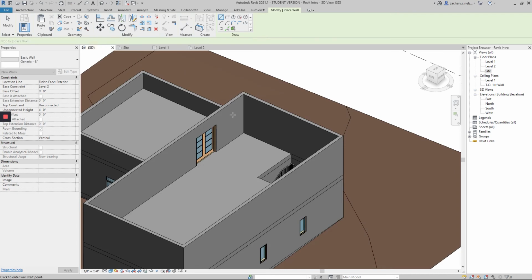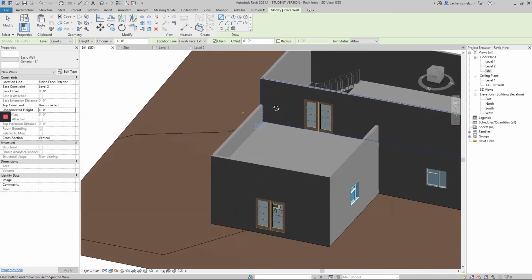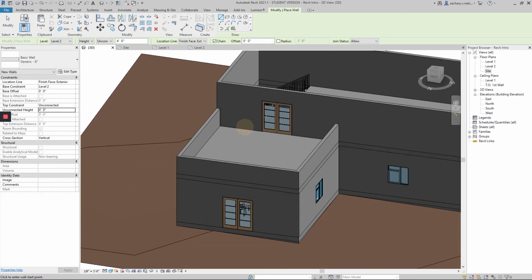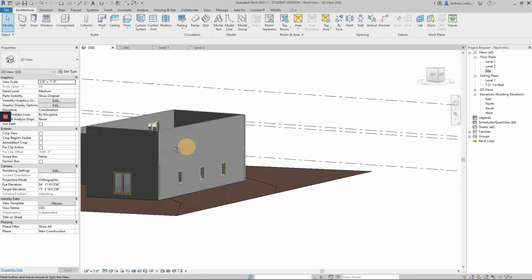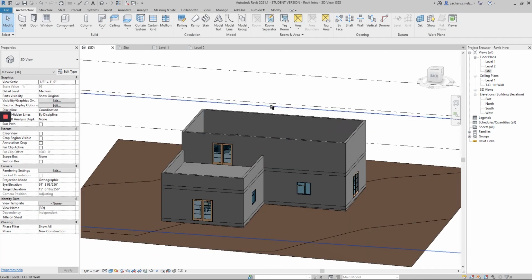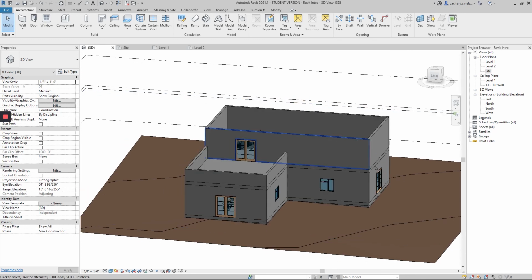And then when I go back to 3D view, you can see that I created that 4-foot high wall there, and I have that nice little outdoor space there. So basically I have an entire building. All it's really missing, I mean you could add a whole bunch of this, it's pretty boring. But to finish off the structure I just need a roof, so let's do that here.